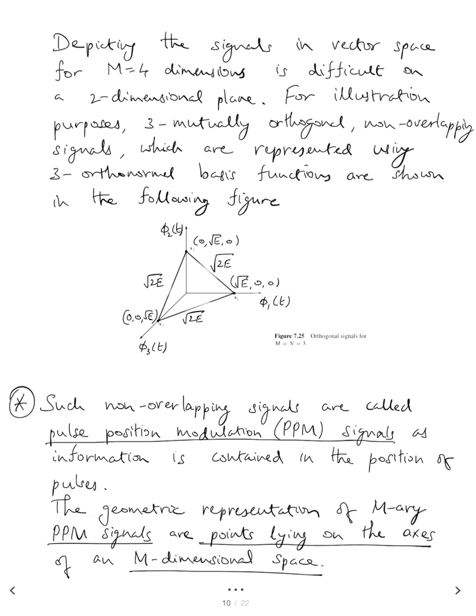We can't see that, but you can intuitively imagine that all the signals will be mutually orthogonal with respect to each other, and all the signals will also have mutually equidistant properties. The distance between any pair of signals is the same. Between 1 and 2, between 1 and 3, between 2 and 3, all the distances are identical, the square root of 2e.